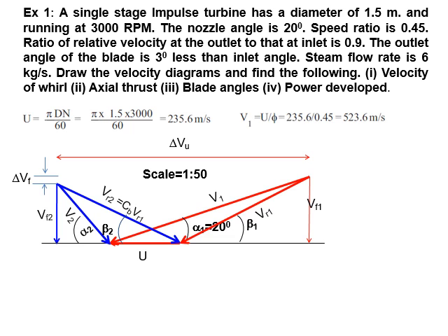Then what about this delta VF? The delta VF represents the difference in heights of the VF1 and VF2. That is the difference of the axial flow velocity lines VF1 and VF2, which is termed delta VF. So measure these two parameters from this velocity diagram, that is delta VU as well as delta VF. After this, list out all the values from the velocity diagram.